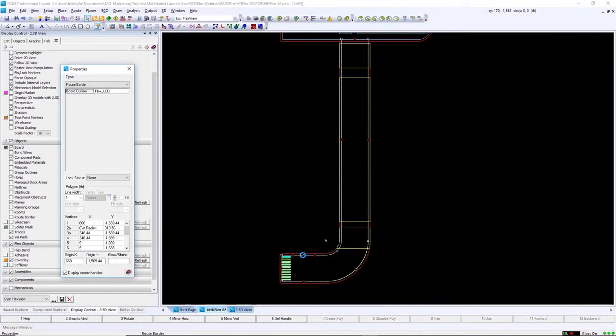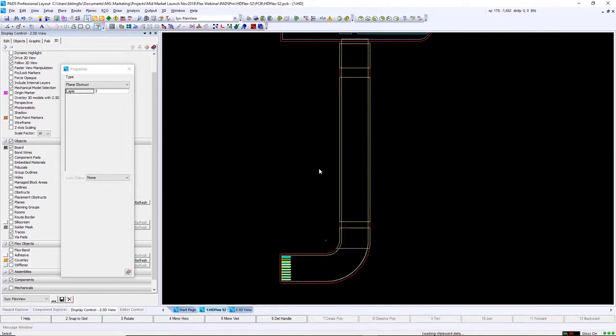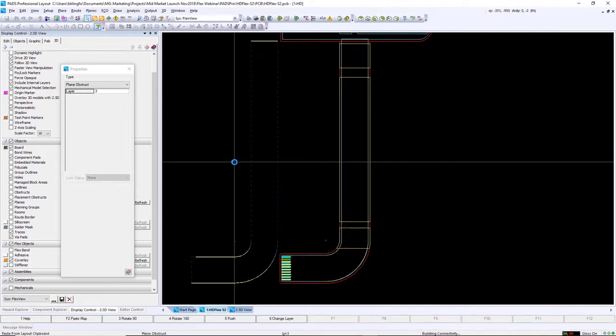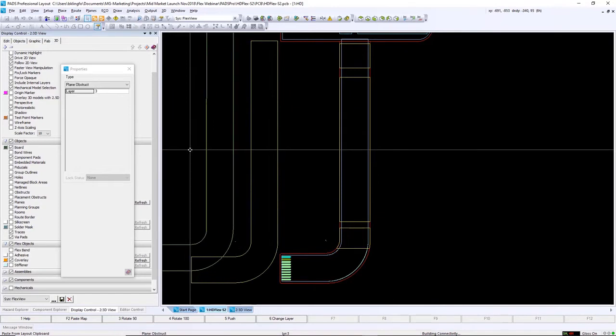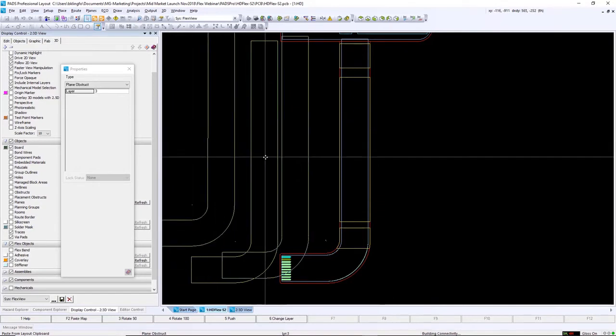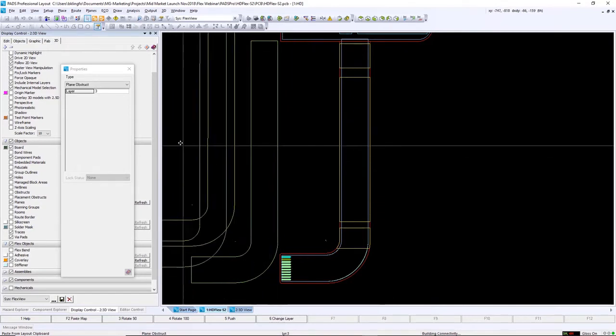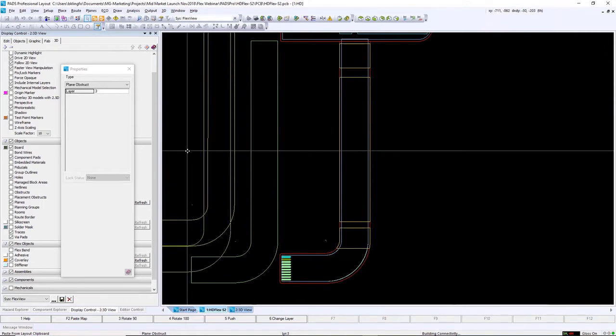We just completed our design rules with a rule area defined, so before we can start routing, we need to place this rule area. While doing this, our design team has decided we should place ground planes in our flex areas. So we will use the shape we created for the rule area to define our planes on the flex by copying and repurposing.